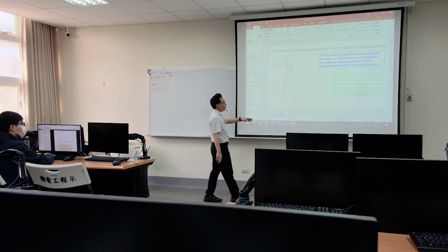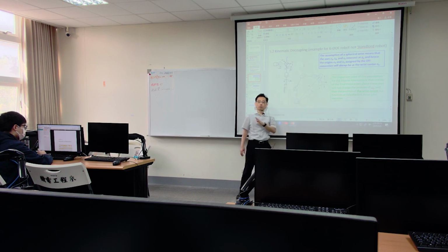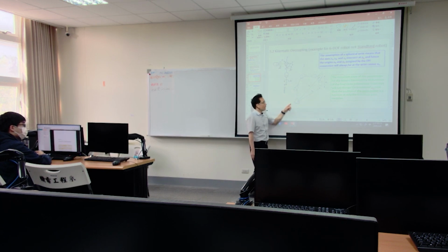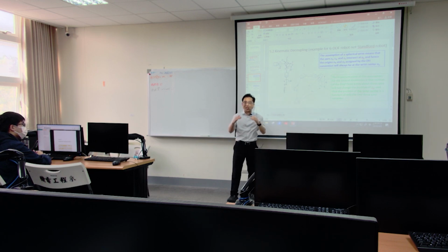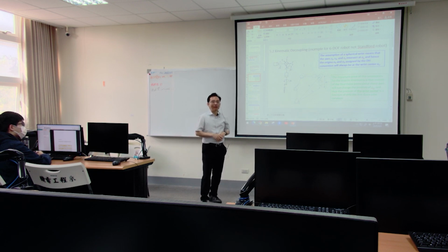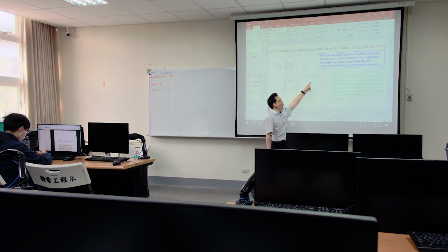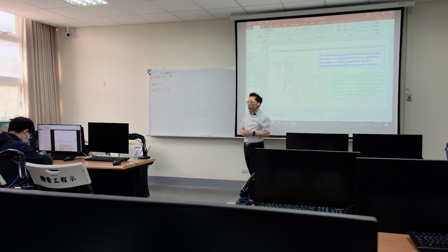We will adopt some information. The first information is the final position and orientation that I supply. And we know the last 3 wrist joints intersect in only one point. We call it O6, and this O6 is what we need to pursue.